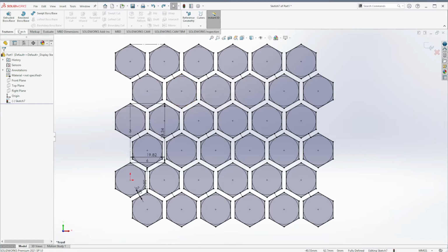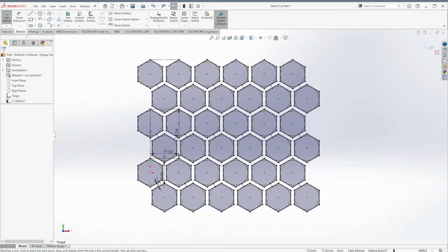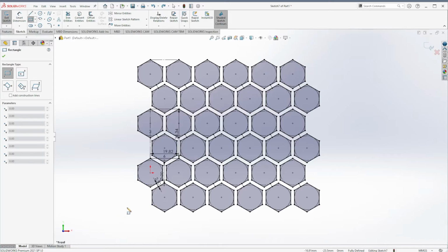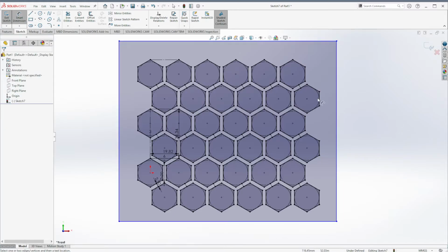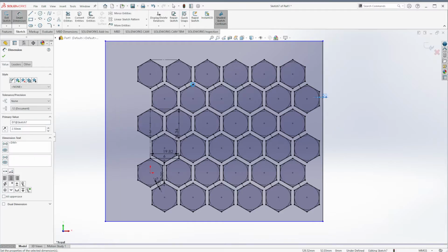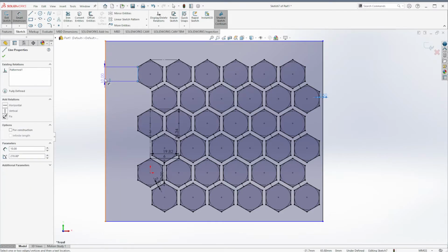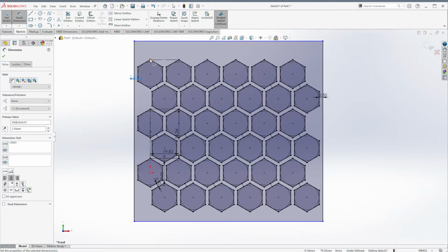If you do want to make this its own 3D shape using the space between the hexagons, what you will want to do is go to Sketch and draw a box around it. Make sure it doesn't catch any of the auto snap points. It's just in free space. Since we fully dimensioned this field, we can very easily connect the box to the edges of the hexagon and it won't completely screw up your drawing. Ask me how I know.